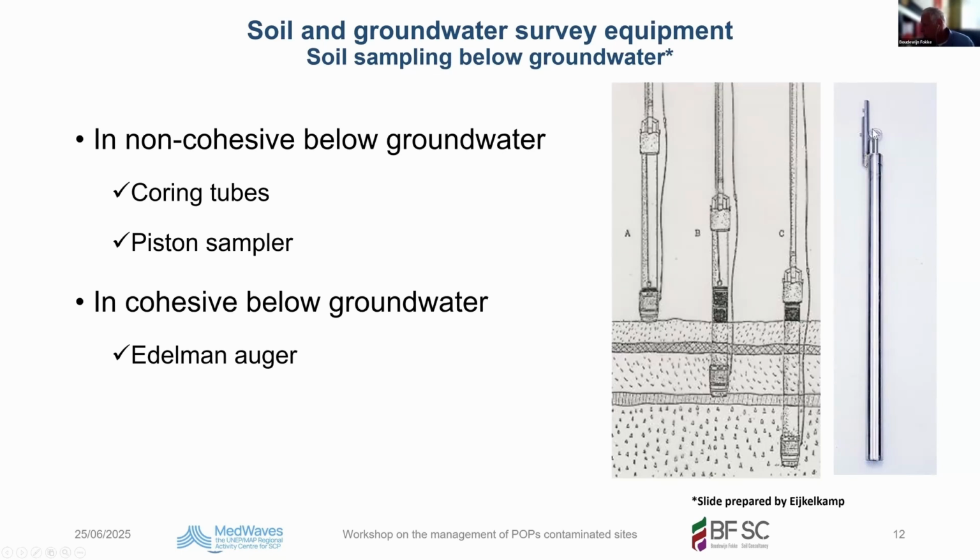You pull this up with a rope, and at the same speed as you pull this ring up, you bring the auger manually down, and in this way the piston fills with sediment. When you take it out, you keep the piston at the last height, then bring it to the surface, press this down, and then the profile is laid on the side above. Now this is the same type, but it's closed with a valve down here.